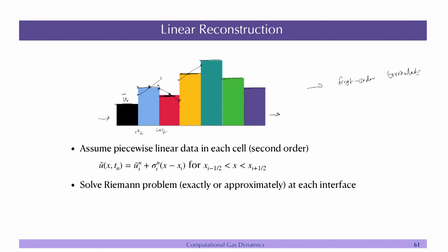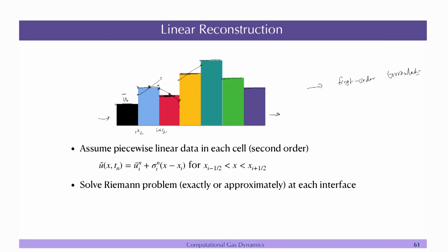We are correcting our earlier assumption that the values remain constant within the cell, to a better approximation, that it varies linearly. If you go to a finite element kind of formulation, you can also go to quadratic variation, with HP formulations, a polynomial variation within the element. But right now we will focus on the linear variation.